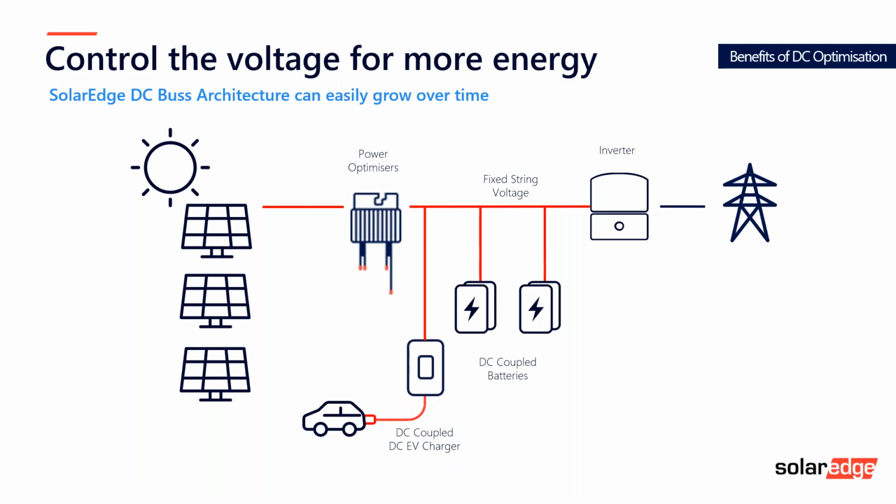And it's a significant feature that's often overlooked at the time when someone is starting out their solar journey. They don't want a battery, they're looking for solar only, so they discount, I guess, the features or the needs that they might need to consider when adding a battery in the future. And too often we see AC coupled systems where the batteries are permanently undercharged because there's no scope to expand that current system that's on site unless you scrap it, which is a costly activity. At least with this, we have that flexibility to expand systems easily over time.